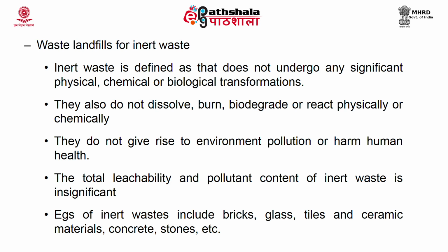Third type is the landfill for inert waste. Now, inert waste is defined as any waste that does not undergo any significant change, be it physical, chemical or biological transformation. They do not dissolve, they do not burn, they do not degrade or react physically or chemically. They do not give rise to any form of pollution or harm to human health. The total leachability and pollutant content of inert waste is highly insignificant. Examples of such waste are bricks, glass, tiles, ceramics, concrete, stones. For this there is a specific type of landfill called the inert waste landfill.